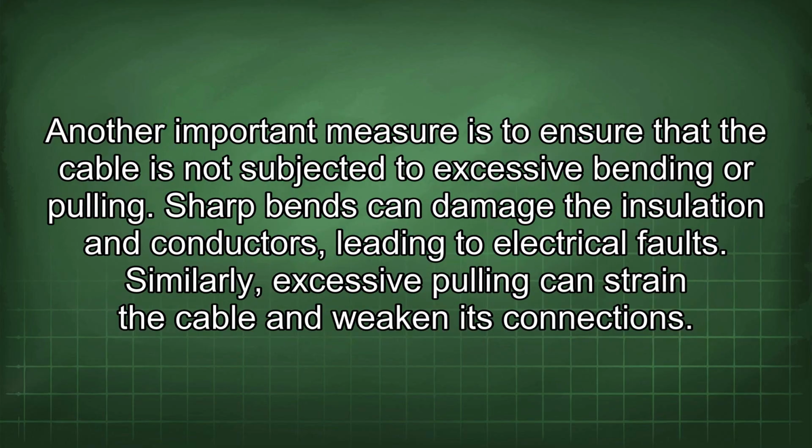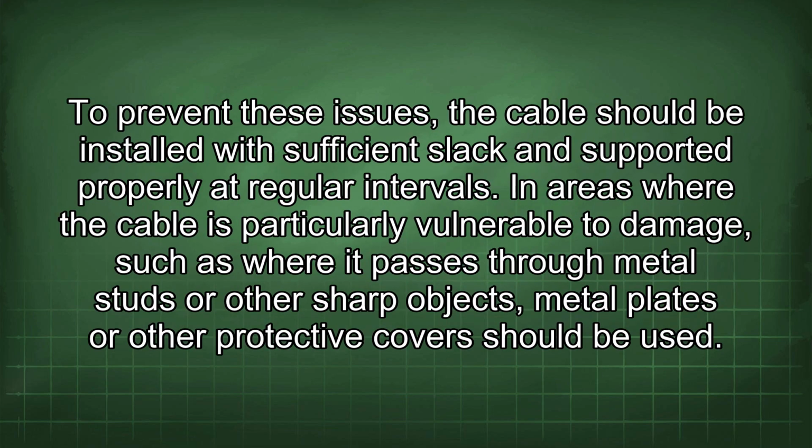Another important measure is to ensure that the cable is not subjected to excessive bending or pulling. Sharp bends can damage the insulation and conductors, leading to electrical faults. Similarly, excessive pulling can strain the cable and weaken its connections. To prevent these issues, the cable should be installed with sufficient slack and supported properly at regular intervals.